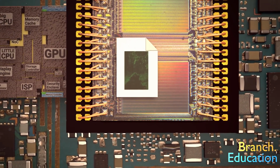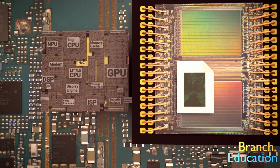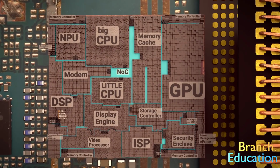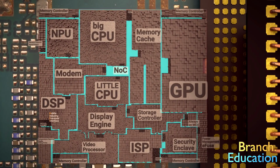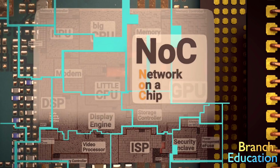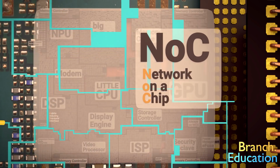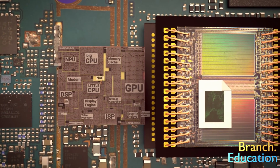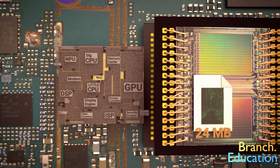There are two quick things to note. First, the data path between the SoC and the DRAM is shared by everything. In this scenario, it's the job of the network arbitrator to prioritize the incoming sensor data of the uncompressed raw image so that no data from the camera is lost, and thus the arbitrator streams the raw image directly into the DRAM. Second, a 12 megapixel uncompressed raw image takes up around 24 megabytes.